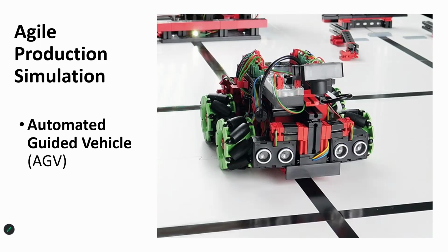The six-axis robotic arm will then place the workpiece that's just been coded onto the automated guided vehicle, or AGV, for further transport. Now, this ingoing and outgoing goods module also contains the central control unit, which is a Raspberry Pi, and it also has the environmental sensor, which measures the different environmental conditions at the factory. Now, there is also an integrated movable camera here, which can be swiveled in two axes and will help to provide insight into the entire factory via the fischertechnik cloud-based dashboard.